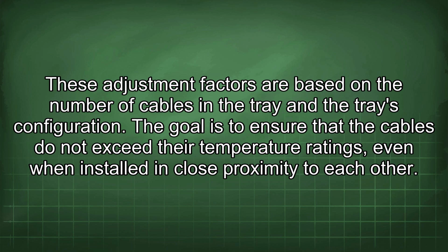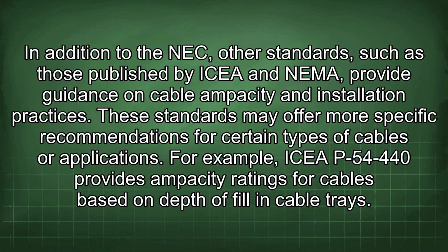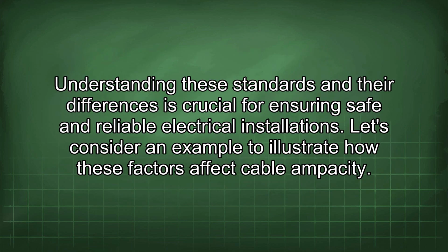to each other. In addition to the NEC, other standards, such as those published by ICEA and NEMA, provide guidance on cable ampacity and installation practices. These standards may offer more specific recommendations for certain types of cables or applications. For example, ICEA P-54-440 provides ampacity ratings for cables based on depth of fill in cable trays. Understanding these standards and their differences is crucial for ensuring safe and reliable electrical installations.